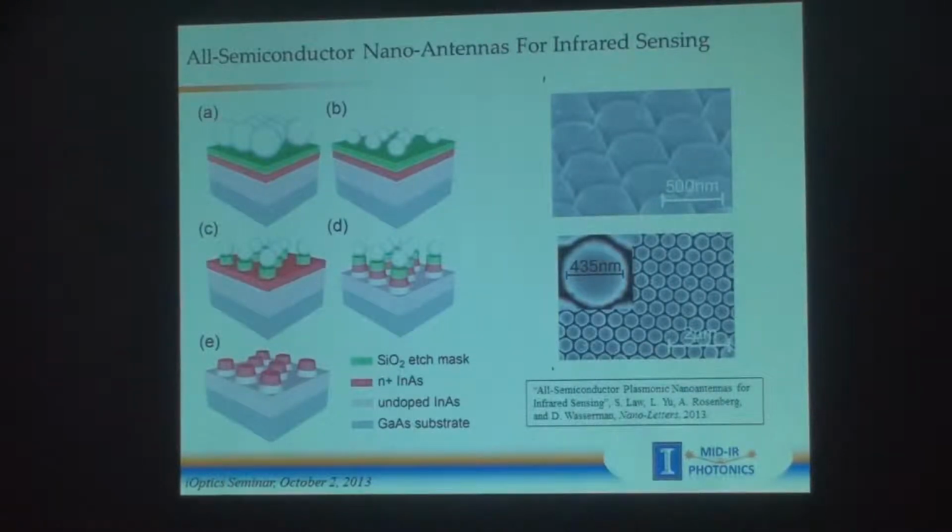They were fairly thick. They were designed to absorb light resonantly. But ultimately, if you want to make a sensing structure, you don't want the thing that's supposed to enhance your sensing doing all of the absorbing. Right? You want the molecules that you're trying to sense to do the absorbing. So what we need to design is a structure that's able to confine your electric field, but without dominating the absorption of that mode. And so we basically just went with significantly thinner structures, so it cut down on our absorption significantly, but still gave us an enhancement of the electric field.